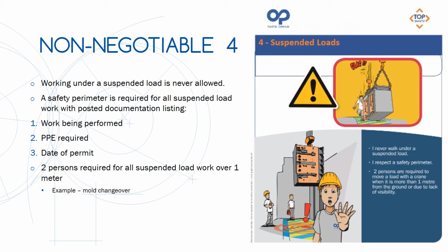Non-negotiable 4. Working under a suspended load is never allowed. A safety perimeter is required for all suspended load work with posted documentation listing: 1. Work being performed. 2. PPE that is required. 3. The date of the permit. 2 persons required for all suspended load work over 1 meter. Example, a mold changeover.